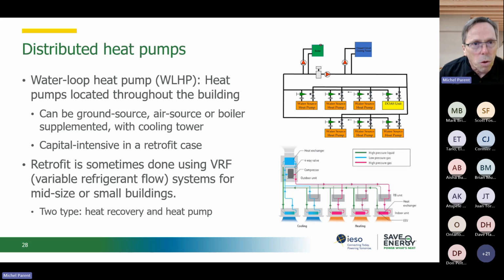This is not going to work, because the heat pumps that you have in the building, in your ceiling space, are a different model. When you have a ground source heat pump system on a distributed loop, the heat pumps are extended, what they call extended range. They need to be able to work with a loop that goes as cold as 0 degrees Celsius. Actually, usually it's 4 degrees Celsius.